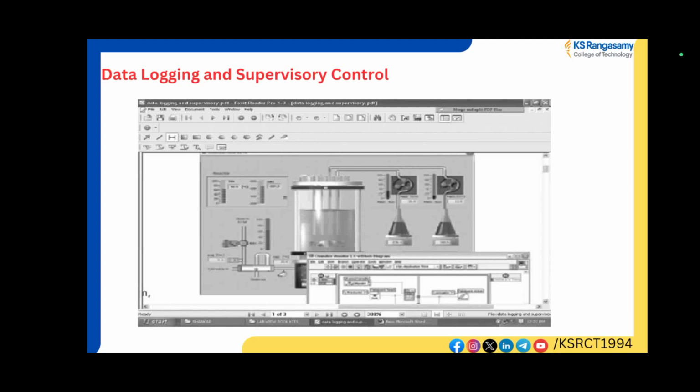Also, the NI LabVIEW Datalogging and Supervisory Control module extends the LabVIEW application development environment to interactively configure and manage alarms and events, efficiently log data to a distributed historical database, view real-time and historical data, set application security, and easily network LabVIEW Real-Time targets and other OPC devices to create one complete system.